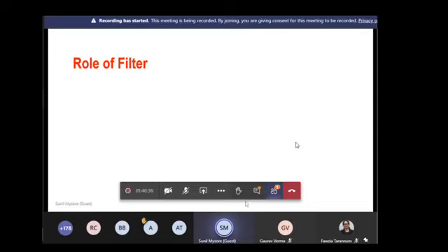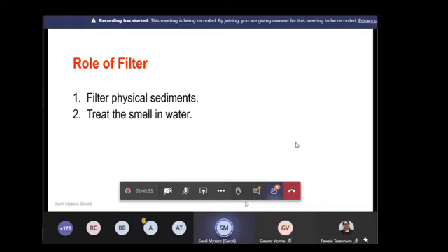You've also taken the subsequent water into the settling tank, but still you're installing a filter. So what does this filter do? If there is any physical contamination like twigs or leaves or dust, it is supposed to filter that. And sometimes, not in southern India but in northern India, I've seen some people complain there's some smell in the rainwater. You have to take care of that.